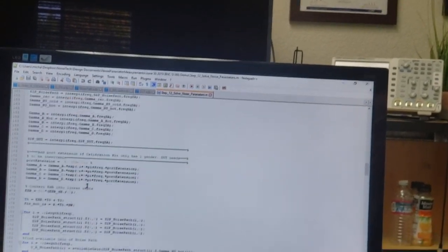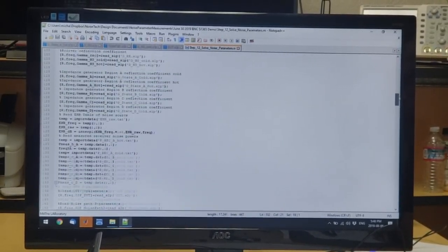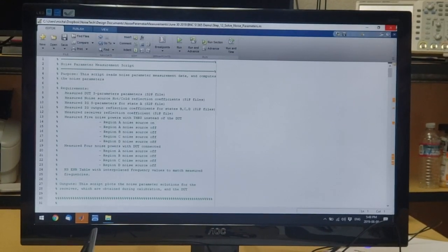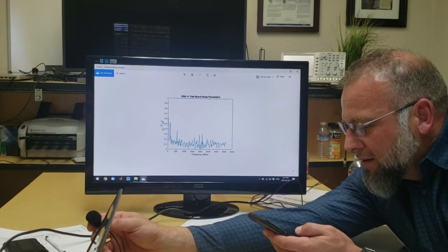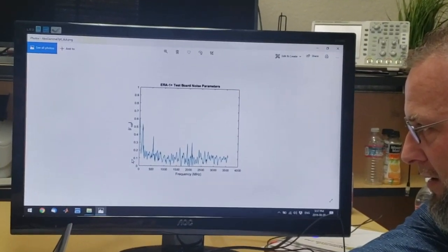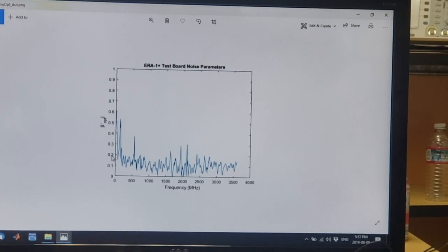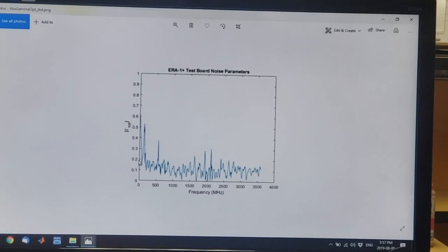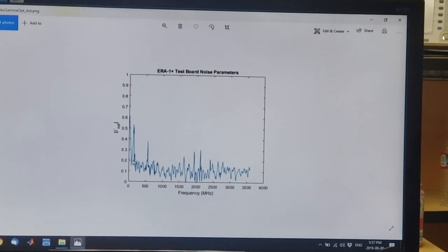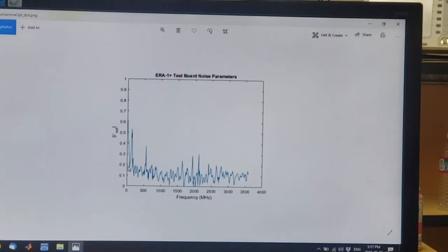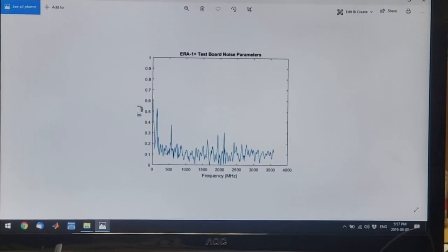They're the first few lines. This is just input file reading. There's a little header here, and then everything else doesn't matter. There's no more file reading till the bottom of the file. The absolute reflection coefficient is actually in linear scale. 0.1 corresponds to 20 dB return loss in the power domain, and 0.2 would correspond to minus 14 dB reflection coefficient in log domain. Generally speaking, anything less than minus 10 dB S11 is going to be well matched.